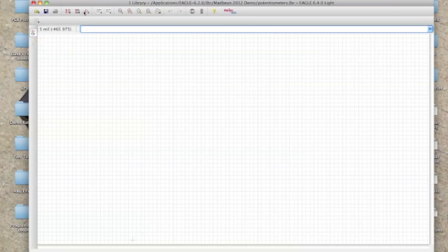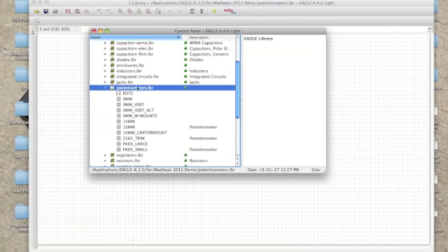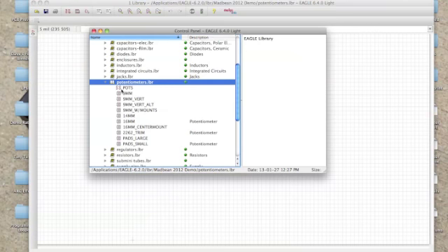On the left here, the only button we have is an edit button. And up at the top, we have some new buttons that we're not familiar with, and then some of our classic buttons that we will be familiar with. These buttons are fairly important. Essentially, they are, from left to right, edit a device, edit a package, and edit a symbol. These are the three elements of every part. The device is the overall thing that we're editing. So, for example, if you open up the potentiometers, you can see this symbol here corresponds with it. Our device is the pots.